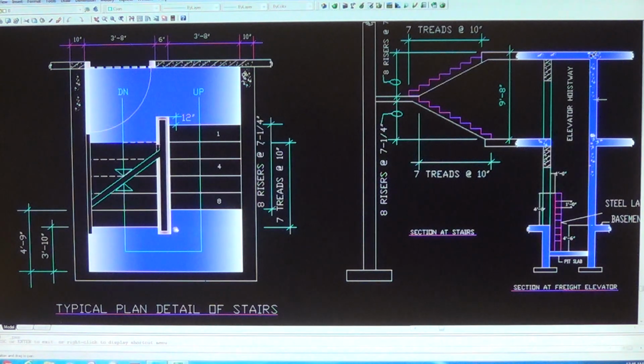No, you can't, you'll fall down when you turn here quickly. One of your feet there would end up on the riser, so you're gonna fall down. Chances are you're gonna fall down when you turn quickly over there. So therefore, this part of the landing, when you switch direction, either in this direction or that direction, it should be extended up to the size of 1 tread.